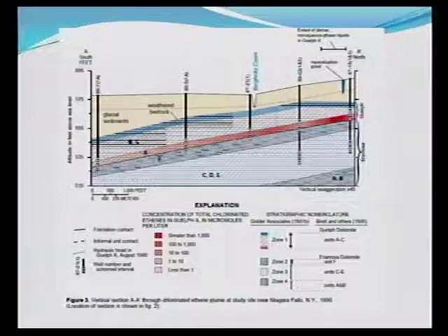But I should have brought back that picture that I showed you last time. What you have to realize is that these fractures are very irregular. They're bedding plane fractures, and the beds are dipping about 2 feet per mile, so it's almost completely flat. And most of the water is moving through these bedding partings. Okay, so if you drill a hole here, and you find that you've got permeability here, then if you find the same place in the strata over here, you're probably going to have permeability there. So my point being that this is a very simple site as far as bedrock goes.